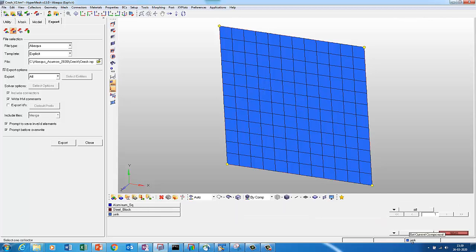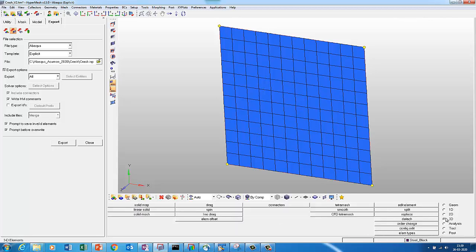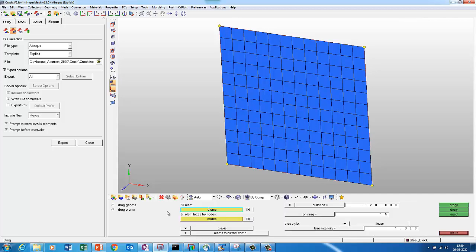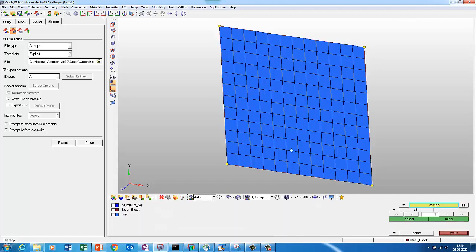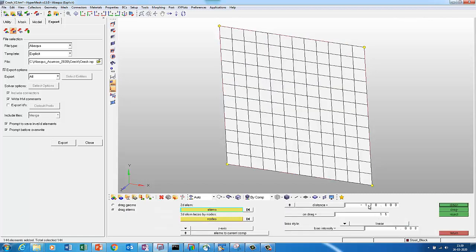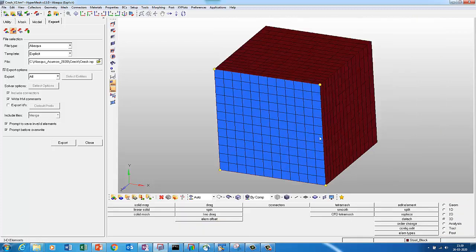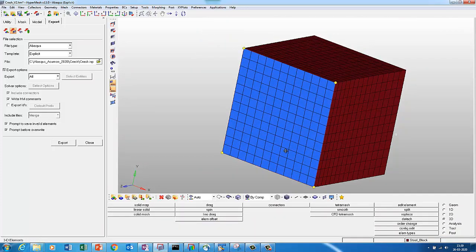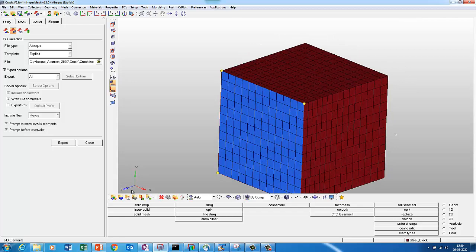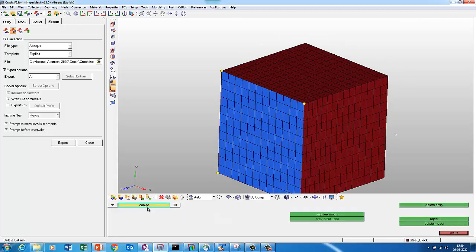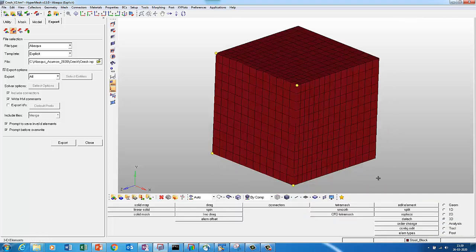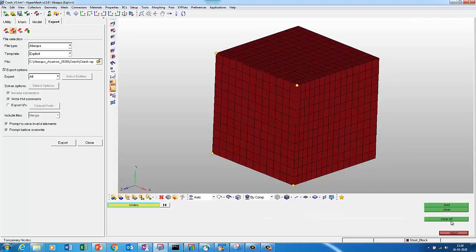So I first go and change to the collector to steel block. I say 3D, I say drag element by collector, and this is distance minus 120, and I say 15 element, and I say drag plus. So it just created a solid block for me. Now what I'll do, I'll say F2, and I'm going to delete this component. I don't want this shell component. So I created now the block.